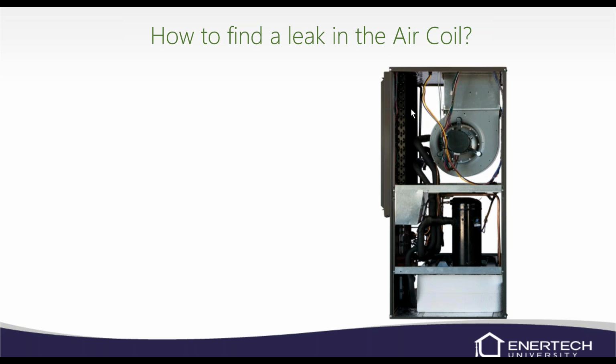If you look at this slide here, it's kind of hard to see, but here you've got the U-bends, and then on the other side, you've got almost like a header, and then obviously you've got the four corners. In one of these four corners of the air coil is normally where I see the leak, and it's right up against the plate there. And so that's where I would check first, is check those four corners.